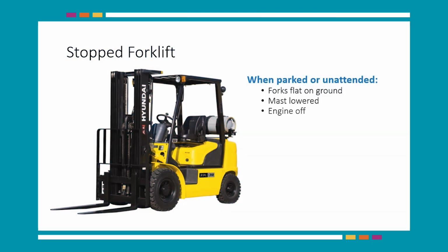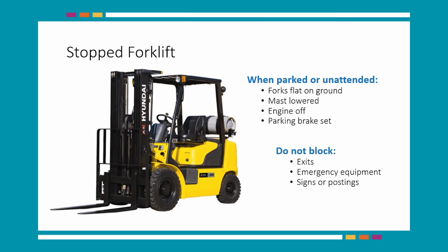When the forklift is parked or left unattended, the forks must be flat on the ground with the mast at its lowest position. Turn the engine off and set the parking brake. Do not park the forklift where it may block exits, emergency equipment, or safety signs or postings.